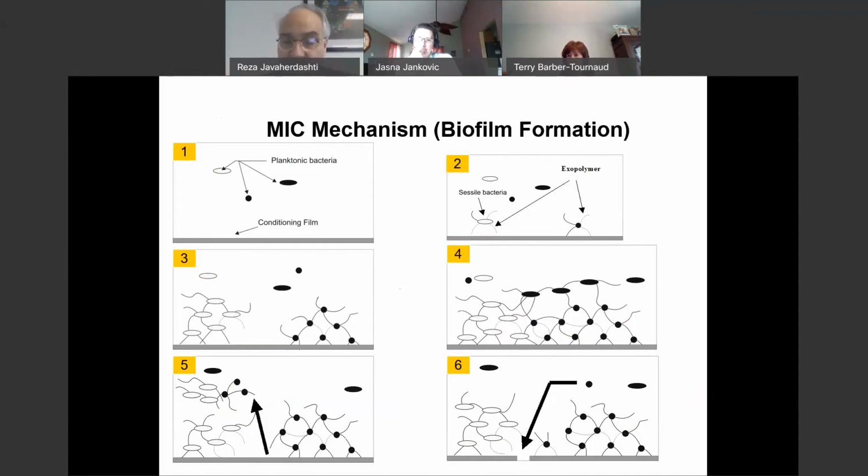Beyond the biofilm here, I'm referring to step 5, beyond the biofilm, it is a low oxygen venue, and here where the part of the biofilm is gone, we have a high oxygen spot. And when you have a low oxygen pressure spot, you will get anodes, and their pitting and corrosion will start under the biofilm.